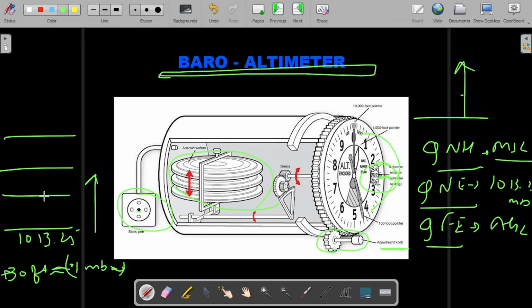So as we are going up, this reduction in pressure is sensed by the static tube, and that goes inside the chamber. When it is at the mean sea level, outside pressure is equal to the inside pressure, which is 1013.25. I'll just change the color. So here the pressure is 1013.25, so altitude is showing 0. A very important catch: if we set QFE pressure inside this, the altitude shown in the gauge will be equal to the elevation or the altitude of the airfield.